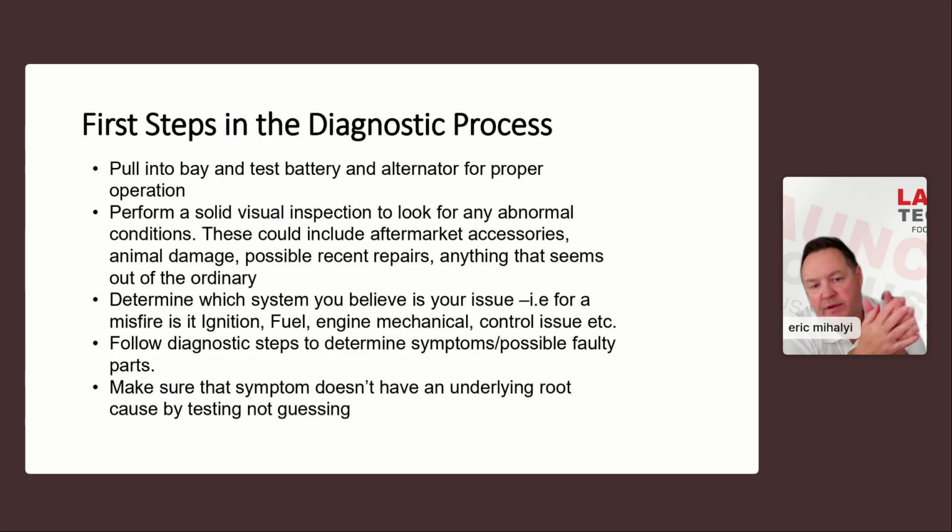And then the second thing is the alternator, right? A lot of times you're thinking about charging output at normal and load conditions. Yeah, that's great. You want to do that too. But the other thing that I look for is the ripple coming out of the alternator. Again, these modern cars are on a network, whether it's CAN high, CAN low. We won't get into all the networks.